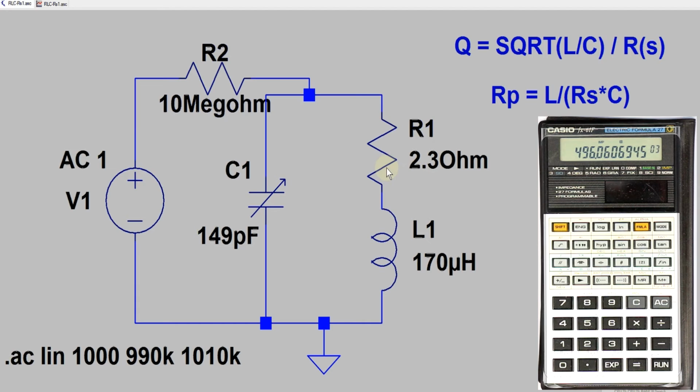There must be more, because we get a much too high Q factor if we only take the measured DC resistance than we have in reality. And second, we can transfer this circuit into an equivalent circuit with a parallel loss resistance.